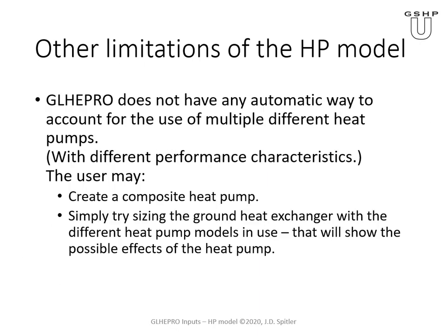Okay, more limitations. GLHEPRO doesn't have an automatic way to account for the use of multiple different heat pumps. I mean, if you're using multiple heat pumps of the same type, the way it works, it will work fine for that. But if you have significantly different performance characteristics, we don't really have a way to account for that in the model.